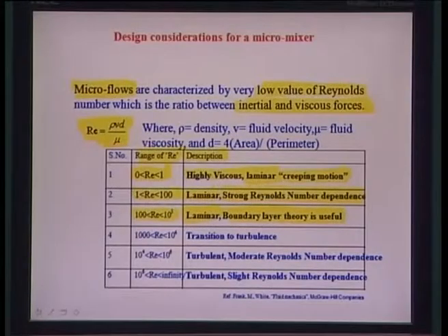So this boundary between the fully developed part and the sheared part of the flow is what the laminar boundary layer is, and it forms very close to a fixed surface, maybe a channel inner wall, or a flat plate or flow over a surface. So this Reynolds number range of 100 to 1000 would have a prominent boundary layer, and here most of the theorizing of boundary layer is very useful.